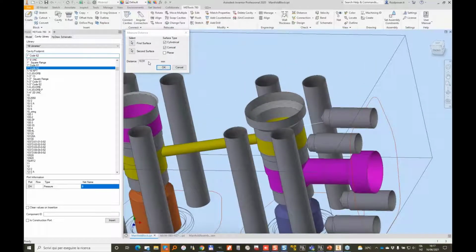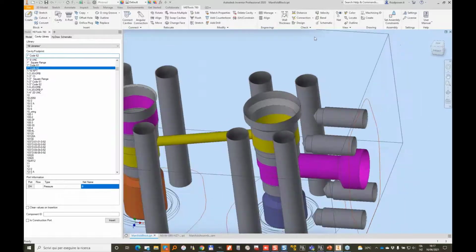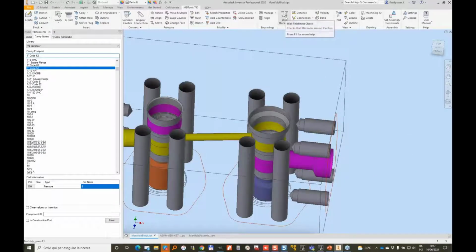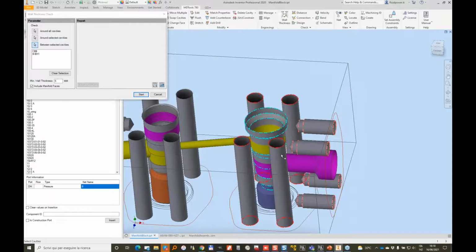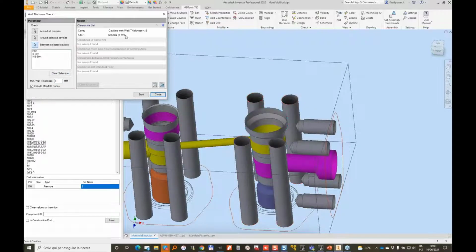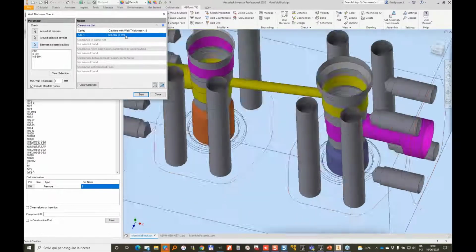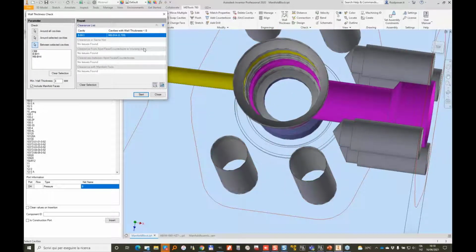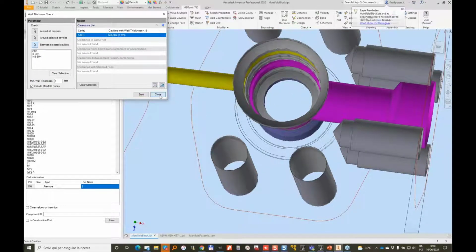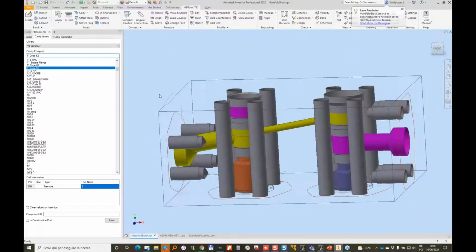This is a lot. I usually don't like to measure distance. I really prefer to do a wall thickness verification. So I want to verify maybe between selected cavities. I want to verify this one with this one and with this one, and start. My limit is maybe, in this case, 8 millimeter. Depending on the size of the drills, you can change the limit. And here you have the minimum distance between these drills, 6.6. That's fine, not a threat. So I live with it.